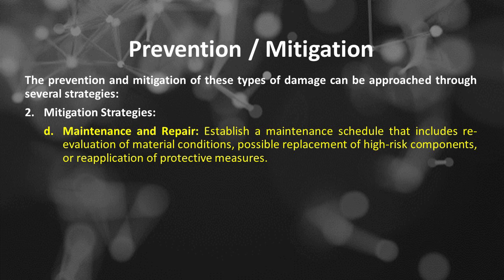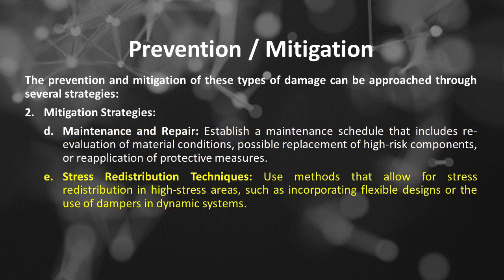The fourth of mitigation strategies to be considered is maintenance and repair. Establish a maintenance schedule that includes reevaluation of material conditions, possible replacement of high-risk components, or reapplication of protective measures. The fifth of mitigation strategies to be considered is stress redistribution techniques. Use methods that allow for stress redistribution in high-stress areas, such as incorporating flexible designs or the use of dampers